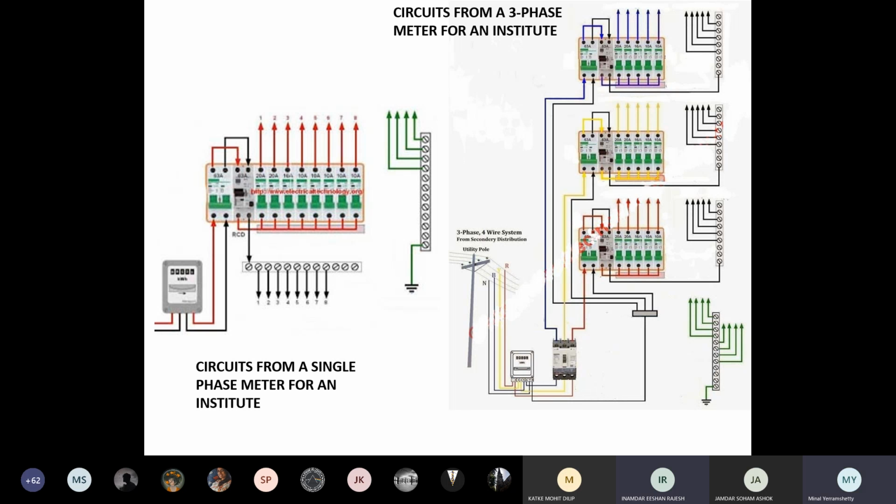We didn't get enough time, which you will be doing now. It's actually third year portion, how you do the water supply for really high rise buildings, say Burj Khalifa. How would you do a water supply for that? It is obviously different from what you do. If I have to handle the pressure, obviously pressure will keep increasing from small to bigger and bigger, so where are my protection points, where it increases to a point, right?